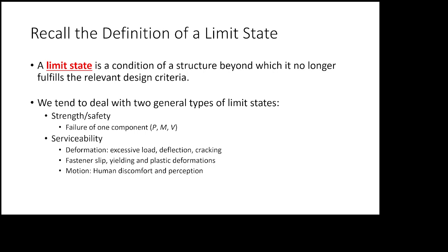While there are some exceptions in some arenas, like service limit states in bridges where maybe some of the load factors aren't one, more often than not, today we are going to talk about what are called load combinations and load factors that are intended to be applied to the strength limit states. Whenever we're dealing with strength limit states in this course, which is honestly what we spend most of our time dealing with, we are going to be factoring the associated loads. But whenever we're dealing with service limit states, we will not.